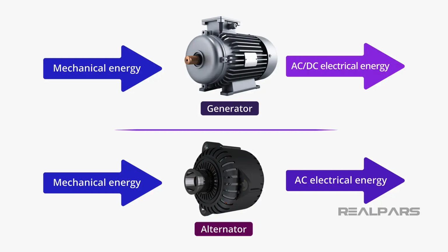This DC source, called the exciter, is generally a small DC shunt or compound generator mounted on the shaft of the alternator. Thus, the rotor winding is energized from the DC exciter and alternate north and south poles are developed on the rotor. When the rotor is rotated in anti-clockwise direction by the prime mover, the stator or armature conductors are cut by the magnetic flux of the rotor poles.